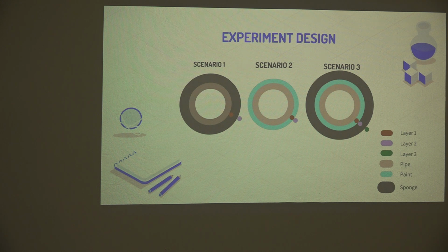From there, with that sensor touching the pipe surface, we painted the coating on top of it, ensuring that we painted over the temperature sensor so that the paint surface going on top of the sensor was of equal thickness to the rest of the paint going around the pipe as well.